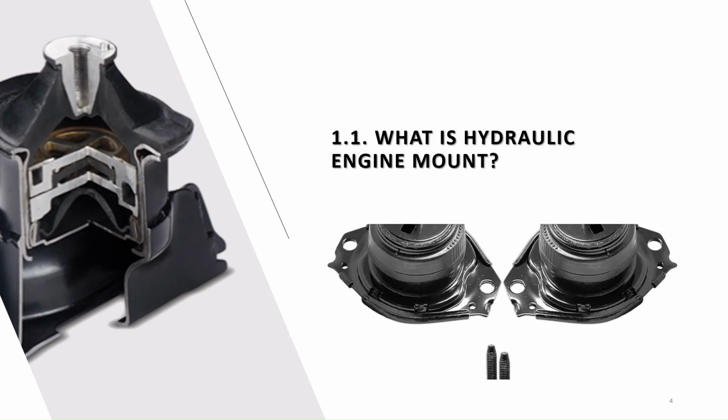Introduction. So, what is the hydraulic engine mount? As mechanical engineering students, you probably study the internal combustion engine class, so you probably have some mindset about the engine. The hydraulic engine mount is usually attached to the engine, and it helps isolate the vibration that transmits from the engine to the chassis. The chassis connects to the frame of the vehicle.